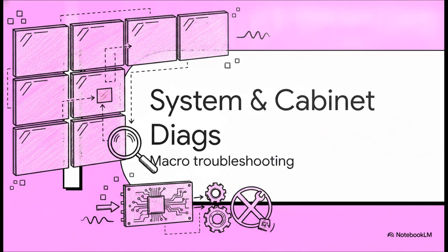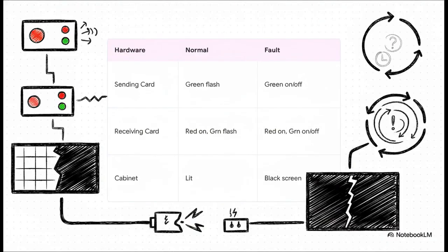All right, moving into Section 1, System and Cabinet Diagnostics. Let's start with the macro troubleshooting. Now, this is where it gets really interesting. You can isolate a system fault incredibly fast just by reading the indicator lights on your hardware cards. It's like they're talking to you. For example, on a sending card, a green light flickering usually just means normal startup or no video input from the PC. But a fast red flicker, that actually means your software license has expired.